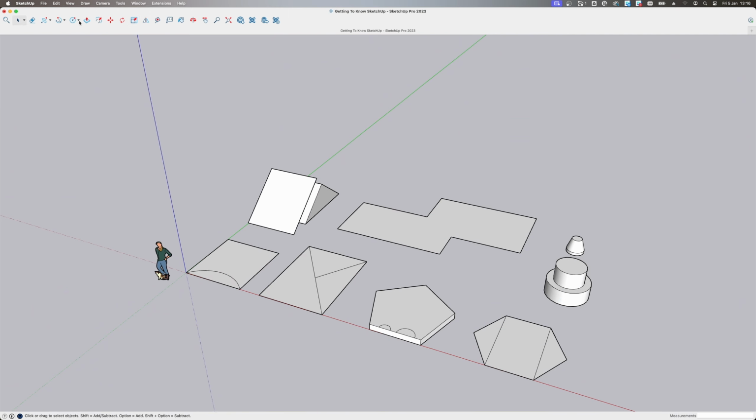Lastly, for the shapes, the polygon tool. In the bottom right corner, you'll see that SketchUp defaults to 6 sides, or a hexagon. Here you can increase or decrease the size to change the shape. For obvious reasons, the lowest number you can go to is 3, which will give you a triangle. Same as before, click to start the shape, drag out, and then click again to confirm.